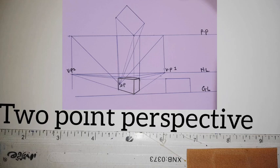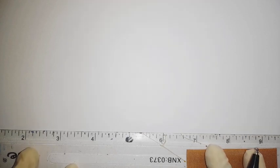Now, when we want to do drawing in perspective, we first have to consider some of the specific lines which are important. The first line that we are going to look at, and which is also very important, is what you call the ground line, and the ground line is also referred to as the ground level. So we draw a line here, and this line we are referring to as a ground line, where an observer stands and is able to see whatever object he wants to see, so that we can do perspective drawing.